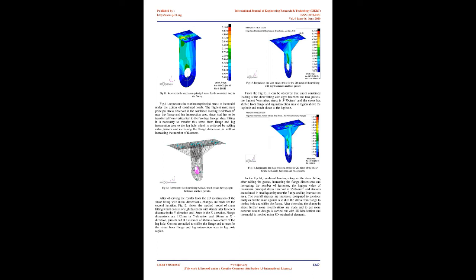When the analysis is carried out, 2 main components are observed: von Mises stress and maximum principal stress. Von Mises stress represents shear critical regions, whereas maximum principal stress represents bending critical regions. Results of this analysis are as shown in the figure below.